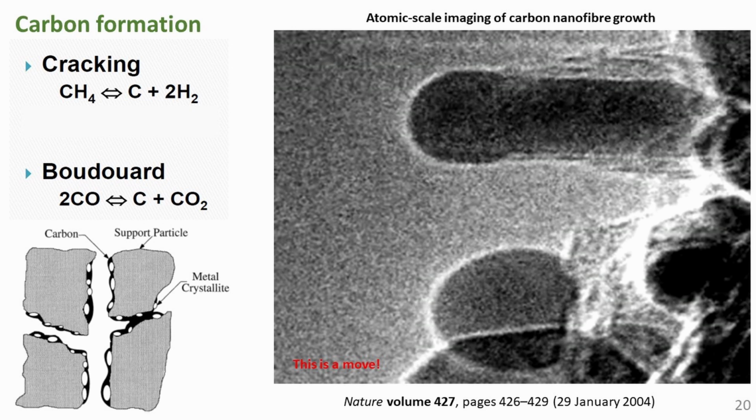Whisker carbon is formed as characteristic fibers from carbon monoxide, methane or higher hydrocarbons and may result in breakdown of the catalyst pellet. Broken catalyst and carbon may have a serious impact on the operation of the reformer.